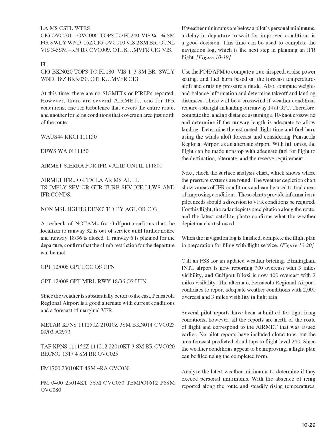There will be a crosswind if weather conditions require a straight-in landing on runway 14 at GPT. Therefore, compute the landing distance assuming a 10-knot crosswind and determine if the runway length is adequate to allow landing.